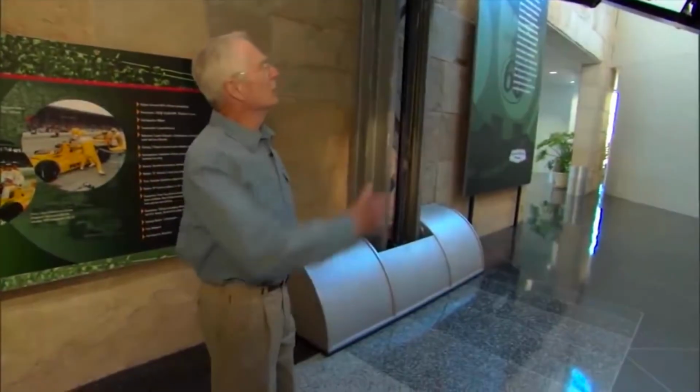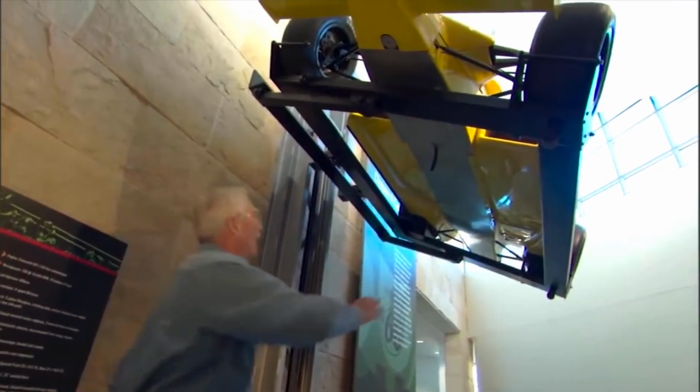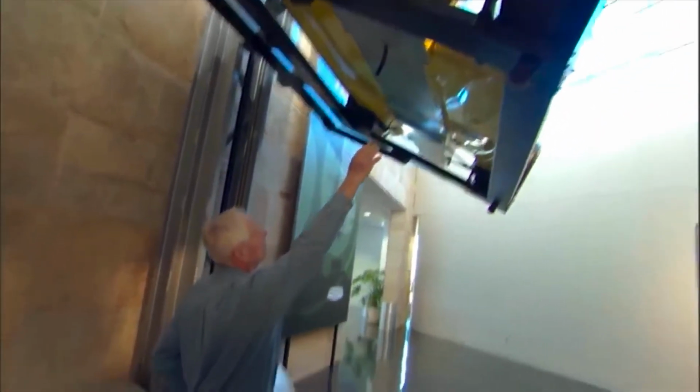And I can show in this video that I have of him, the basic idea is the Bernoulli principle that we've seen: if you get velocity to go up, your pressure goes down under the vehicle. And this was an extremely successful car. The way this car makes more downforce is through a channel on the bottom of the car where the air flows. It all happens in the side pods, not in the middle. It happens underneath the radiator opening.